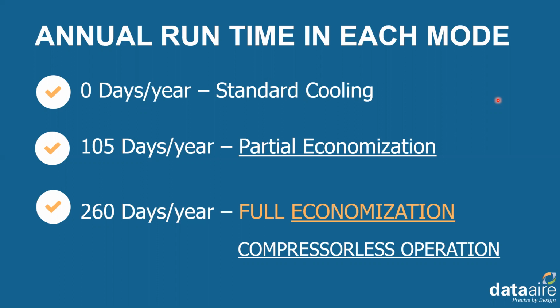So the dry bulb design in LA is 91, and the wet bulb design is 70. But if you go to Atlanta, the dry bulb design is 94, and the wet bulb is 74. So 70-degree wet bulb versus 74 is not that much different. The wet bulb design is also 74 degrees in Dallas and in Phoenix.